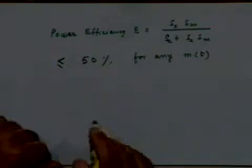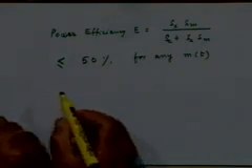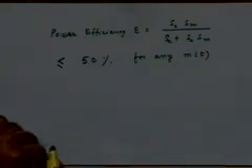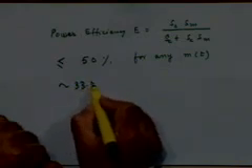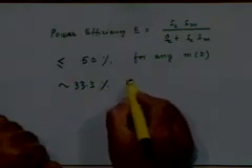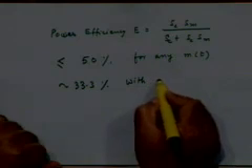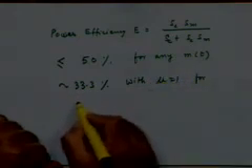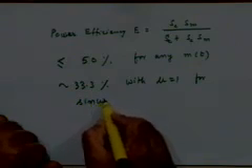In fact, if you take your message signal to be a sinusoidal signal, like the one which we are discussing here, then one can show very precisely, and in fact I would like you to do that as an exercise, that in that case the efficiency is of the order of 33.3% with the modulation index of 1 for sinusoidal modulating signals.